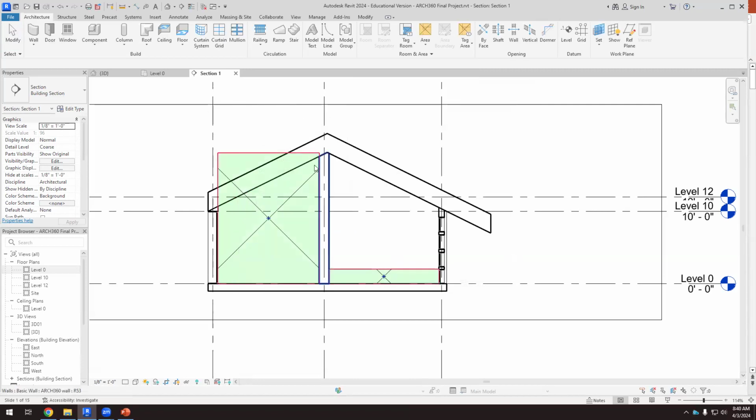If we click OK, this is what happened. Okay, so this is what you will find by default in Revit. If you don't select the areas and volumes, the space will be something like that. So when you have a flat roof, you can work with this because you only have to check the right height for the space. But when you have a tilted roof and you don't compute the volume, that weird thing happens. And of course, that will give you an incomplete result because the space is not enclosed.